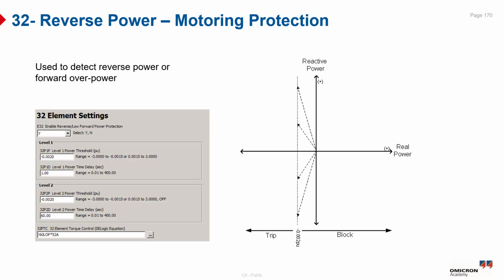When the energy input to the generator from the prime mover stops, the generator begins drawing power from the system to cover its losses, a condition detected by the reverse power relay. The required relay sensitivity depends on the prime mover. Steam turbines under full vacuum typically need from 0.5 up to 3% of the rated kilowatts, while non-condensing units may need higher settings.